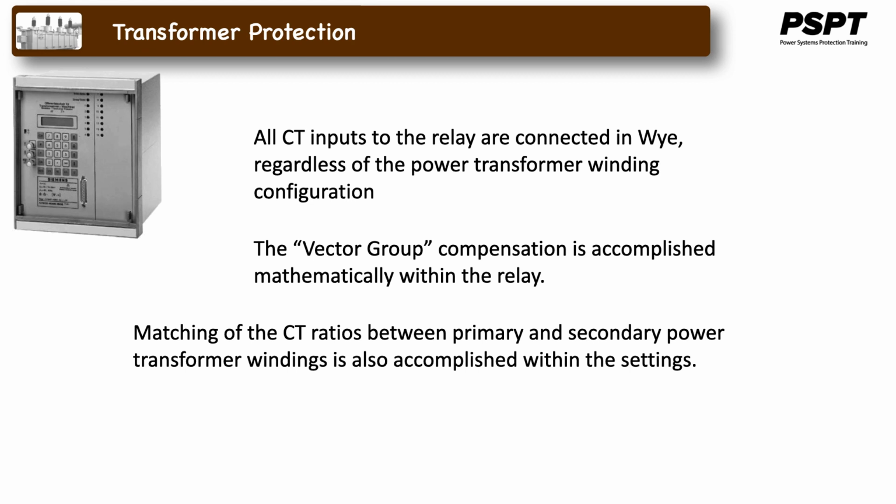The relay has 3 main sets of 3-phase CT inputs and a capability of having 2 additional single-phase neutral CT inputs. The user defines which windings are referenced to the primary and secondary windings of the transformer. The single-phase inputs are used for restricted ground fault and ground overcurrent protections. The relay contains 2 independent thermal overcurrent elements that can be associated to any of the 3-phase CT inputs. These elements model the actual thermal behavior of the protected windings.